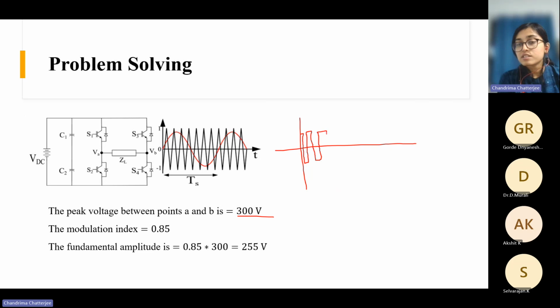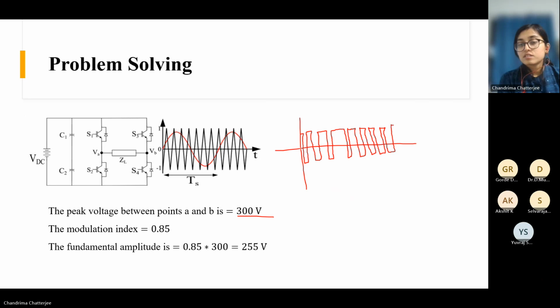Gradually it will increase like this, and then again it will reduce, just like a sine wave. The sine wave is embedded in the pulse, that's why the widths are like this. So the embedded sine will be something like this, and in the negative half also. Okay, but the amplitude is what? Exactly equal to VDC, right?